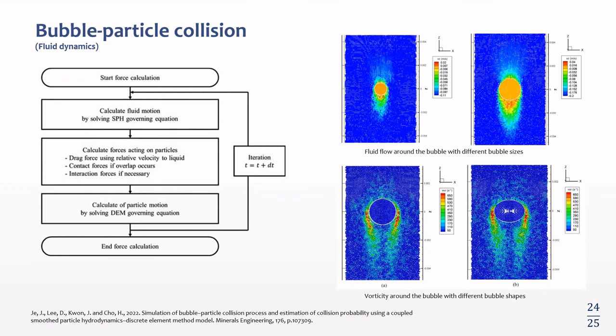This is so important, and these insights that SPH can give us help us understand what happens in the froth flotation environment and how these particles and bubbles interact with each other, how the particle moves, and the hydrodynamics of the process. We can predict the efficiency of the process and figure out how to enhance this efficiency by generating different shapes of particles or different sizes and shapes of bubbles, or changing the viscosity and properties of the surrounding medium, in order to manipulate the hydrodynamics of the process.